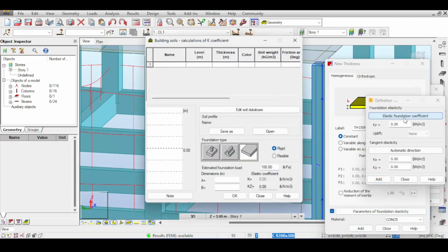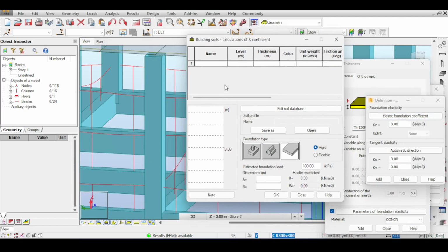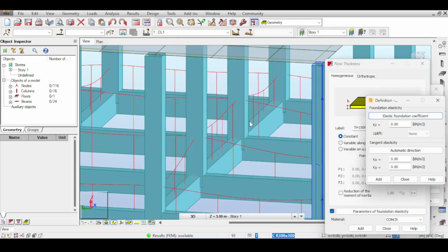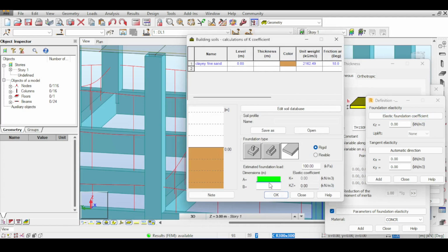And I go to elastic foundation. Now you need to define the very same soil, because it's impossible to have two different soils. This time I'm going to leave the check, since there was a video about rafts, so I'll leave that for you. The raft here is 9 by 9, so there we go, 9 by 9, and it should be calculating. What about the pressure?